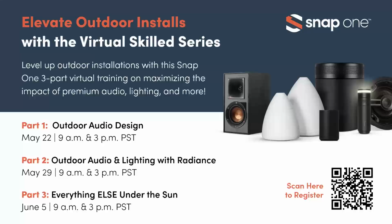The Terrain system comes as a 4.1 kit. You can buy 2-speaker accessory pair add-ons to build up to an 8.2 and still stay at or above the 4 ohm impedance on a multi-channel or 8 ohm amplifier. The benefits of that system are that it's quite a bit more cost effective and a lot simpler, because you can just use standard 8 ohm amplifiers instead of a special amplifier like this hybrid amplifier. The downside is that you're really restricted in the size and scale you can make the system.